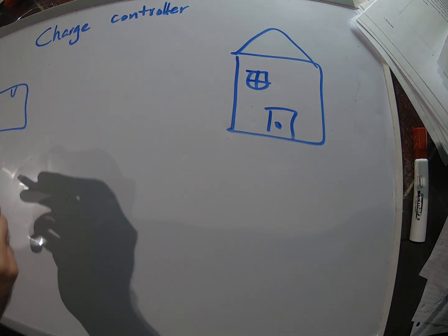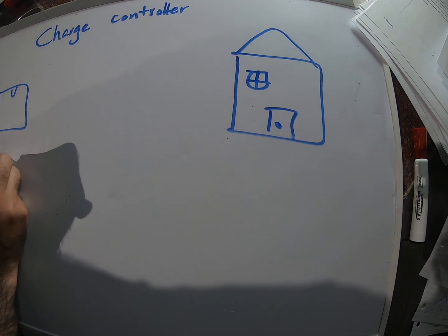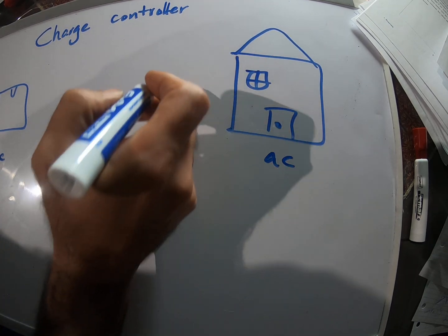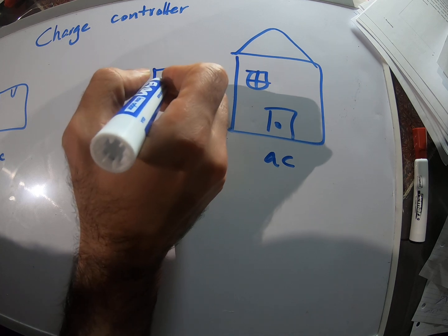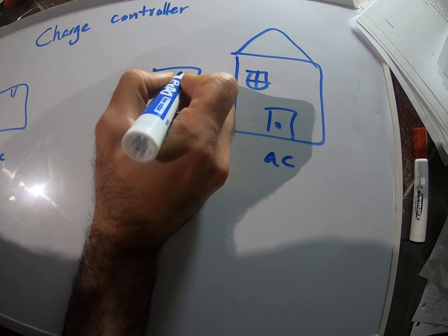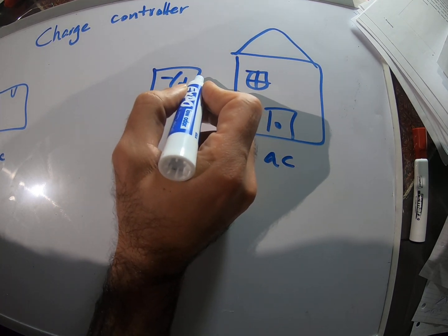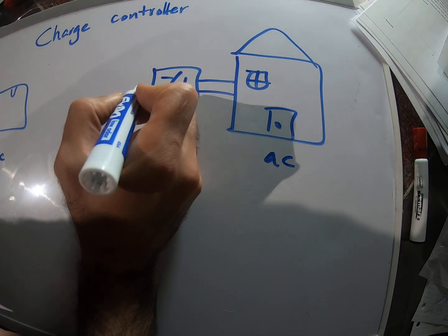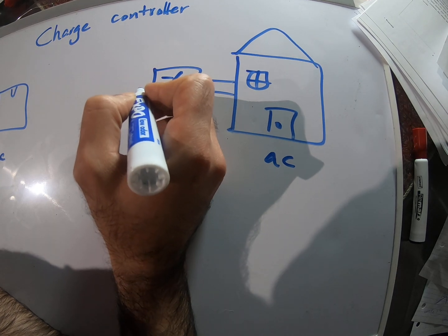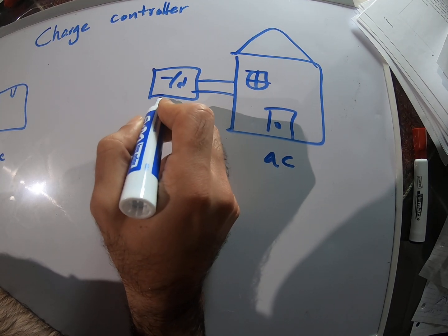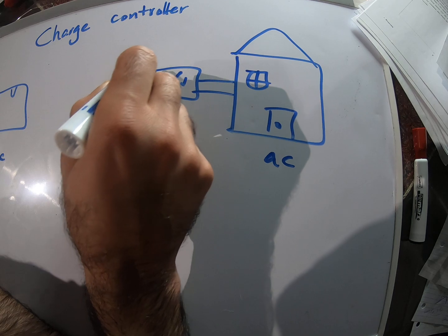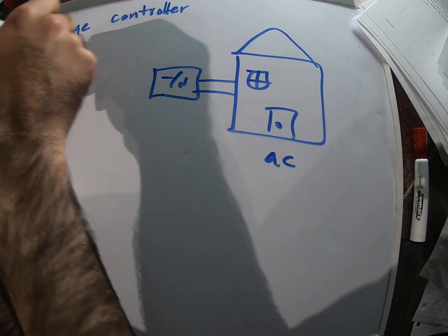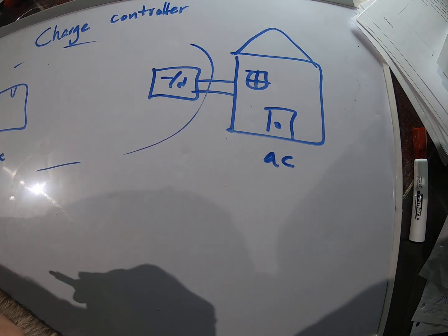Okay. So this would generate DC, this would need AC, right? So we saw last time that we need an inverter here, so we can have an AC voltage here. Many times our MPPT algorithm would be implemented in the inverter. Okay, so this would adjust the voltage here.